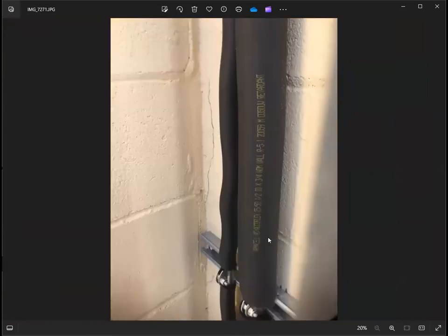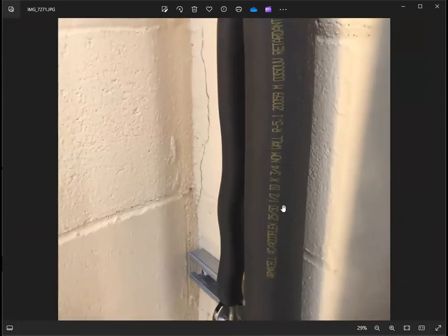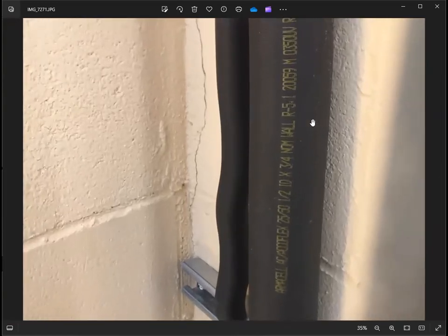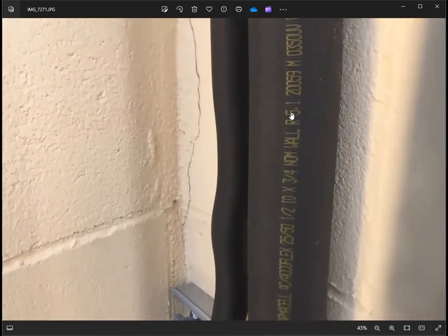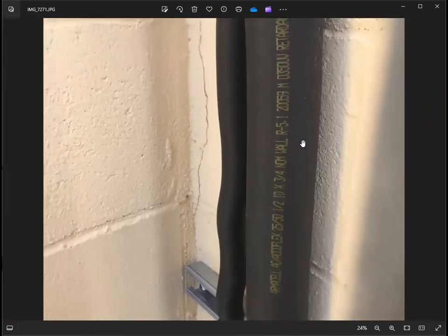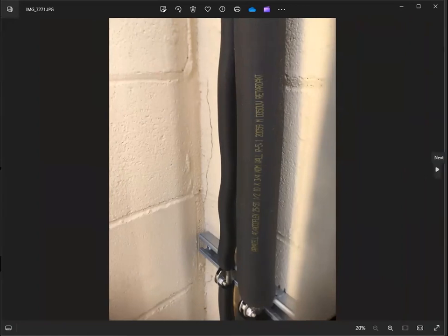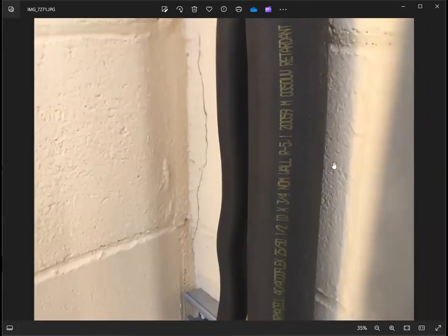And piping of the refrigerant should also be insulated. I need to identify the thickness, and the R value is 5.1. I see the requirement for refrigerant piping is R3, so this is acceptable. R 5.1 is more than the R3 value.